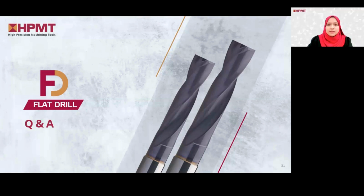It is recommended to use coolant when using flat drills because we want to prevent the tools from overheating, and also increase the tool life and enhance the chip removal, since it is drilling. However, if you do not want to use coolant, you need to make some adjustments to the cutting parameters. But in case you're unsure about this matter, you can contact us and get advice from our application team if you want to know more about this. So I'll pass back to Nana.